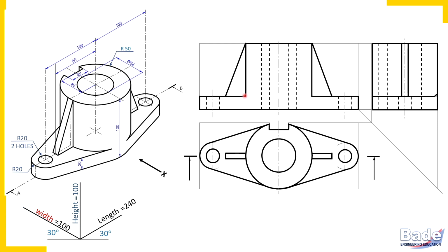Never cut ribs, or in another way, you can remember in this manner: when the largest portion of a plate appears in sectional view, then that plate is assumed uncut. So we have assumed that this plate is not cut, and therefore there will be no hatching lines here, and that is why these two lines will remain as they are.